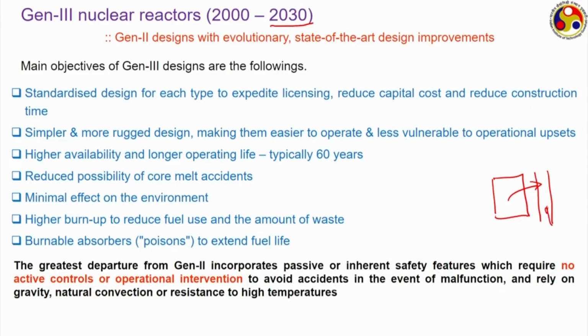Now, a lighter fluid always likes to move in the upward direction, whereas a fluid which is cooler is also heavier and likes to move down, and that is a phenomenon that we can always take advantage of. As the fluid is moving upward in this direction, its density is continuously reducing, thereby providing an added potential to move in the upward direction.